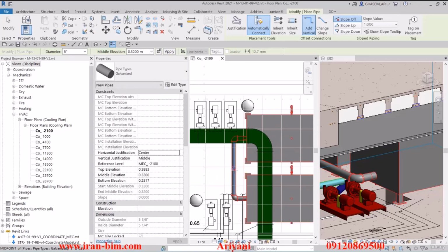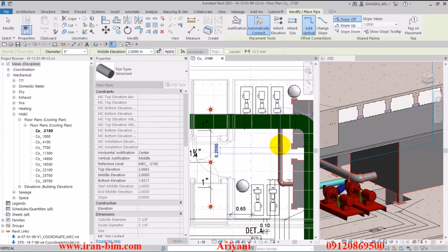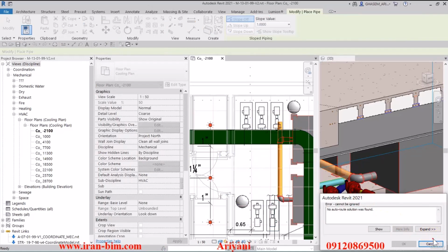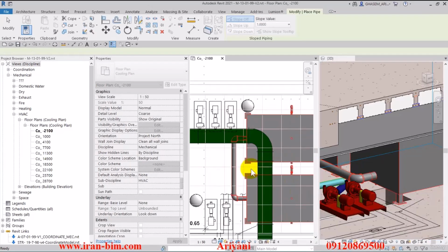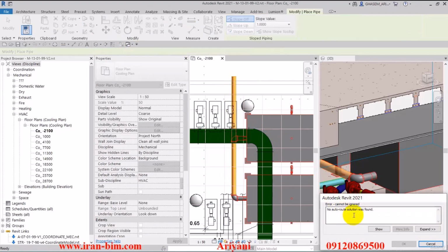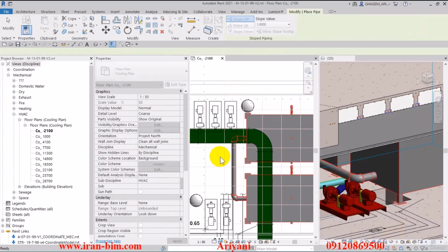Alright, so now we'll select the point from about the halfway line of the pipe here. Put in about, for example, 2 meters for the elevation point. And then we'll go over here and click here. Now we'll have to adjust this as well, but we can hit cancel for now. To try this once again, put it in 2 meters of elevation and then hit apply. Now let's bring it up here.